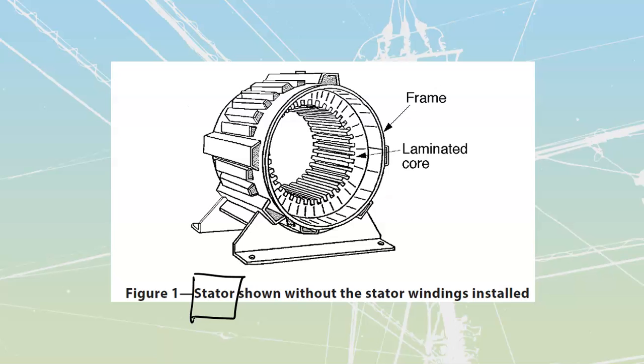And the beautiful thing about three-phase motors is they are so incredibly simple. What we will have is the stator, which they show us over here. That stator is then going to have laminations that are going to be placed in here with slots so that we can place our windings inside of those. The laminations are there just so that we have fewer of our stray losses, skin effect, hysteresis, eddy current, dielectric, fewer of those associated AC losses, particularly the eddy current losses that we are going to have.